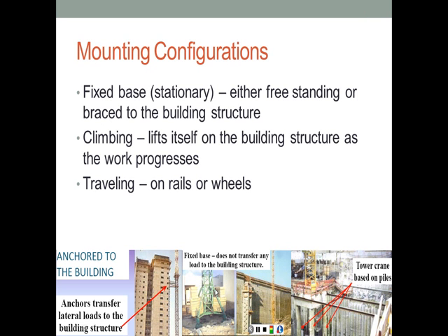The fixed base does not transfer any load to the building structure. So here it transfers the load directly to the ground. And here we have a tower crane based on piles. So it has to be very well positioned to avoid any lateral motion.